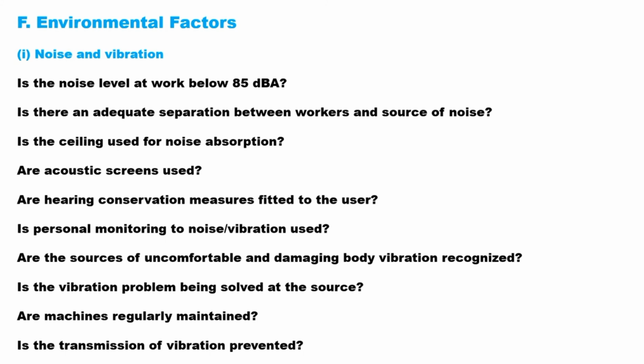Is personal monitoring to noise, vibration used? Are the sources of uncomfortable and damaging body vibration recognized? Is the vibration problem being solved at the source? Are machines regularly maintained? Is the transmission of vibration prevented?